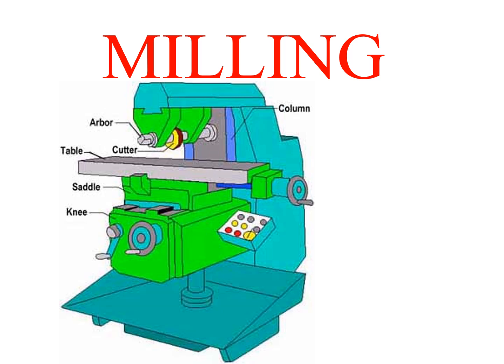Next, feed rate. Feed rate is the velocity of the feed movement of the cutting tool relative to the workpiece in the milling process. Generally, linear feed rate is adopted in practical production and it is defined as feed per minute. The feed rate of milling will directly affect the machining accuracy, surface quality, deformation of the workpiece, and tool life.